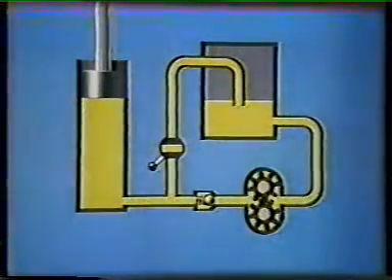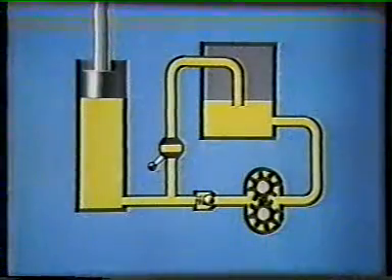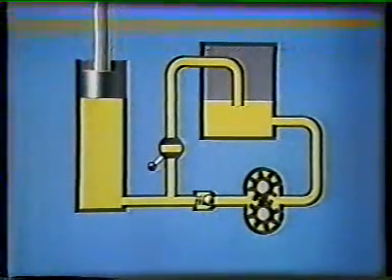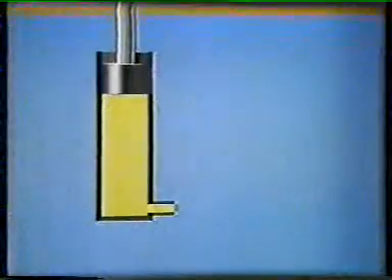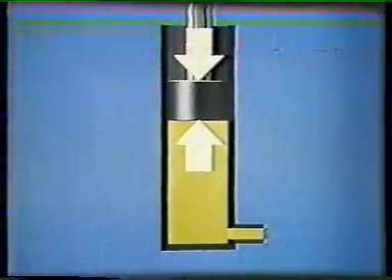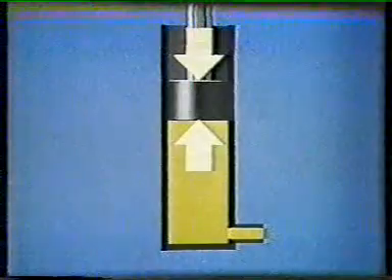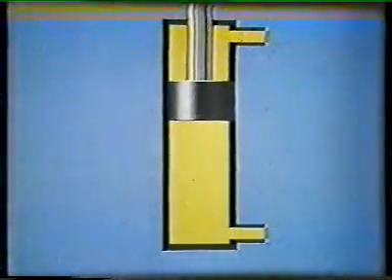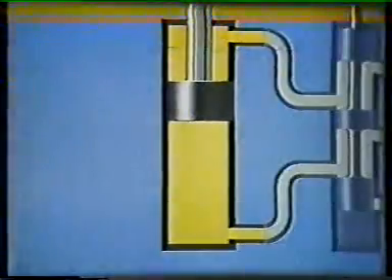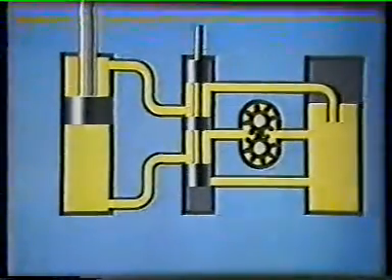So far, we have seen simple lifting and force magnifying applications of the hydrostatic principle. Sophisticated applications require a system that controls the movements of the piston in both directions, which means that hydraulic fluid is introduced to both sides of the piston. To allow the pump to be used for both control directions of the piston, additional pipes and a control valve are required.